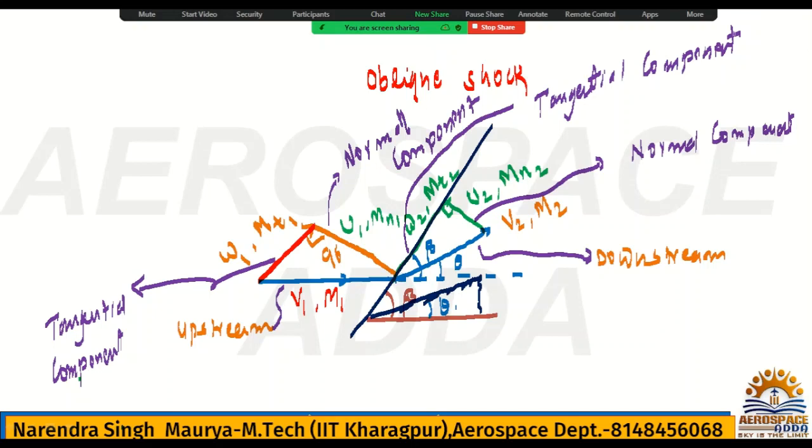Okay, hope this one is clear to all. All right. Now check this. Now we can have the equations. We need to write all the quantities, like M2, that is the downstream Mach number, and obviously the upstream pressure P1, rho 1, Mach 1, and I have already shown you V1.